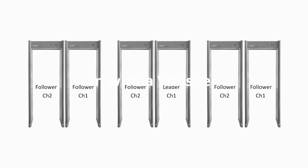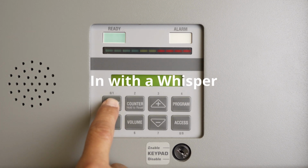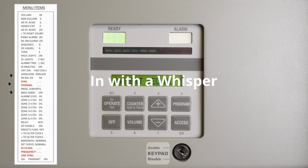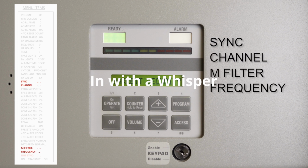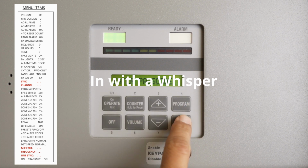To set up the PDI unit as the follower, make sure the leader unit is already on and all follower units are off. Identify your first follower unit and turn the unit on by pushing Operate. To set up a follower unit, we're going to modify 5 menu items: sync, channel, M-filter, frequency, and line sync. To access the unit, press Access, followed by 5, 6, 7, 8.